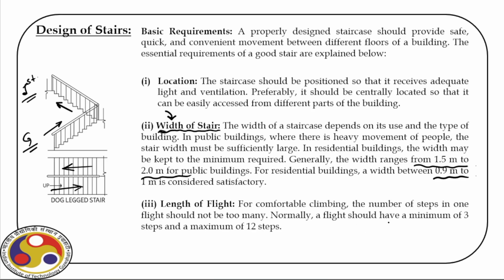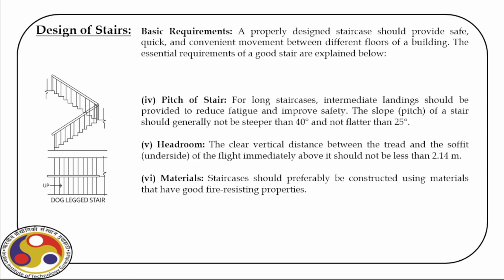Now, normally there is a thumb rule that each flight should have a minimum of 3 to a maximum of 12 steps. So, when we design the geometry of a stair, we should keep that in mind to design the number of steps in a particular flight. There are some other requirements also. Pitch of a stair. As you can see here, this stair is moving in this direction and there is a half landing here, and from this half landing again it moves towards the next floor.